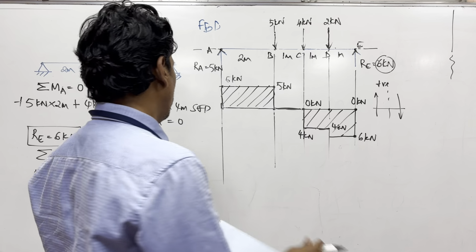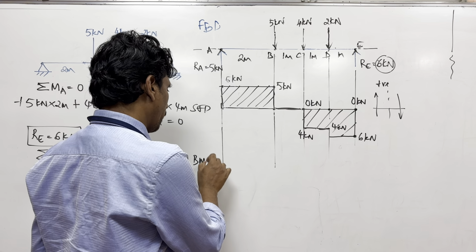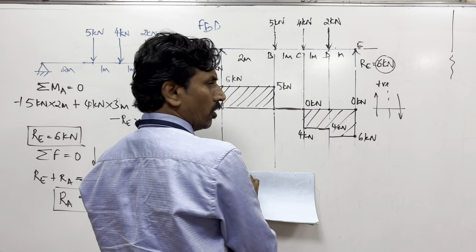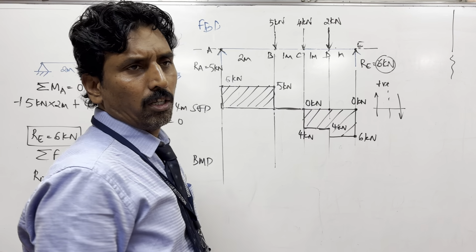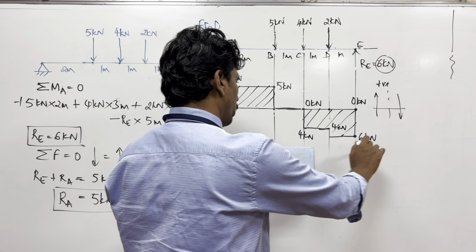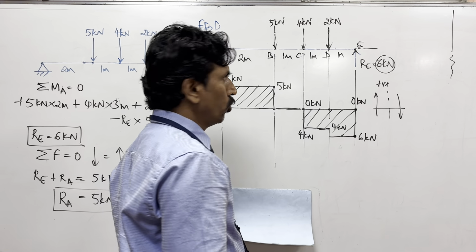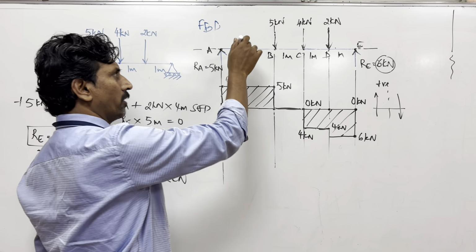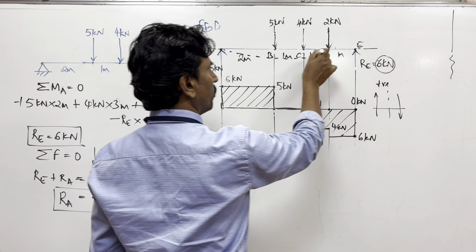Now you have got the shear force diagram drawn. Once it is drawn, you need to draw the bending moment diagram. Again, you need to draw the 0 line. Usually students will have a doubt whether to draw this line very close to this or should I draw here. Usually what happens is, when you have supports like this, the beam would bend like this.